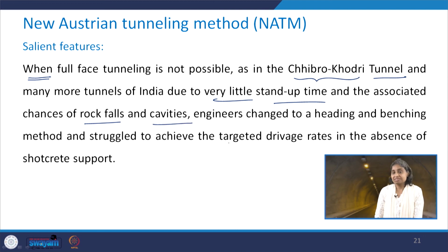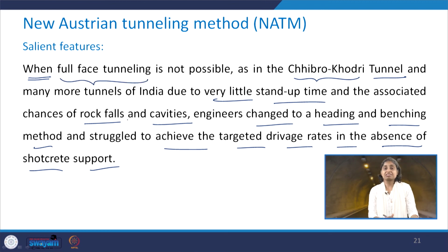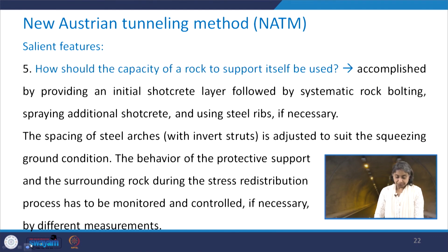What engineers do is change to the heading and benching method, and they really struggle to achieve the targeted drivage rates in the absence of shotcrete support. So it may not happen that for all rock masses you are able to go ahead with full face tunneling. If this is not there, then we have a few difficulties.